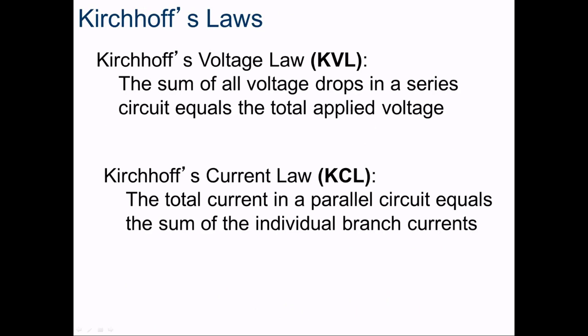Kirchhoff's voltage law: the sum of all voltage drops in a series circuit equals the total applied voltage. The sum of all the voltages in a series circuit is equal to the total voltage. Kirchhoff's current law: the total current in a parallel circuit equals the sum of the individual branch currents. This can be summed up, you might want to write this part down.